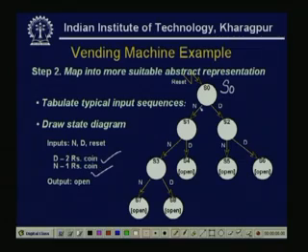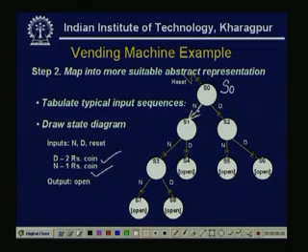We have not considered any 50 paise coin or 25 paise coin, only two inputs we have taken. So, if now I deposit a 1 rupees coin, it proceeds further, because there are chances that another 2 rupees coin may be deposited or another 2 number of 1 rupees coins can be deposited. So, a state transition occurs from S0 to S1.